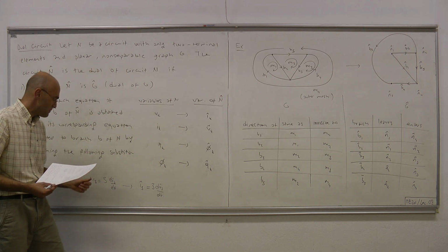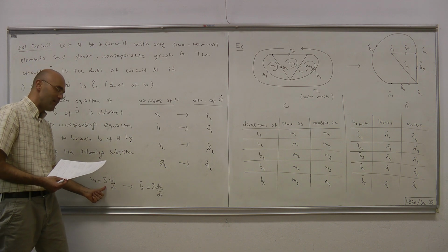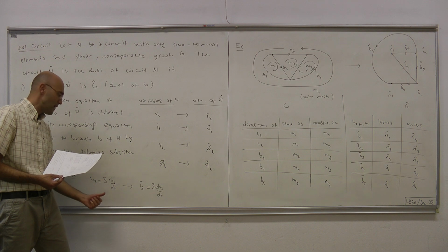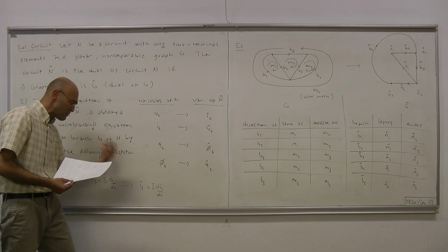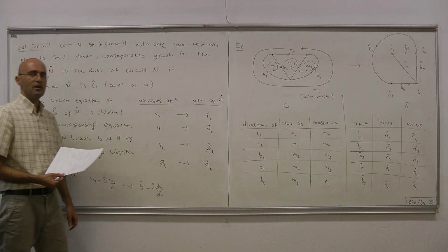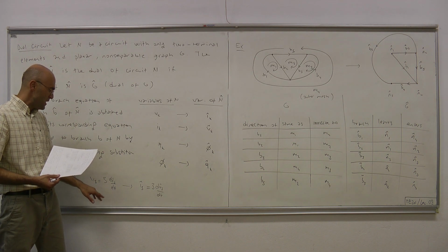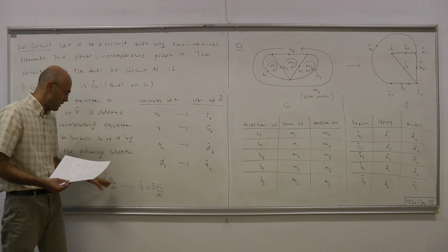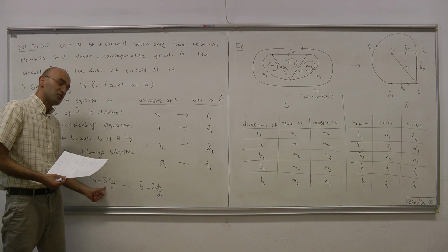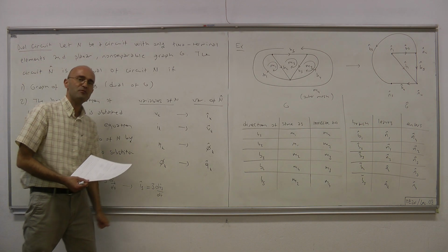And the relation between inductance and capacitance for the dual component is such that here we have an inductance of 3 henries that describes this component, and that 3 henries becomes 3 farads describing the capacitance of the dual capacitor. It's very simple. Or V3 equals 3 times I3, let's say. Forget about this di3 dt. So we're talking about an LTI resistor with resistance 3 ohm. In the dual circuit, it becomes I3 hat equals 3 times V3 hat.